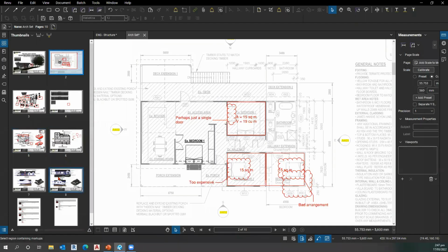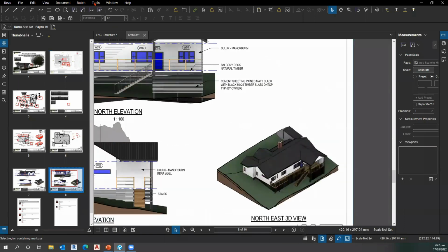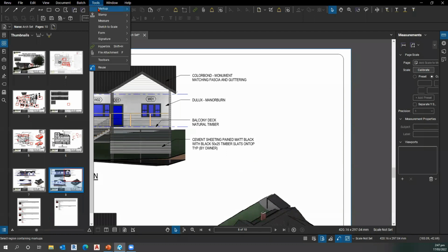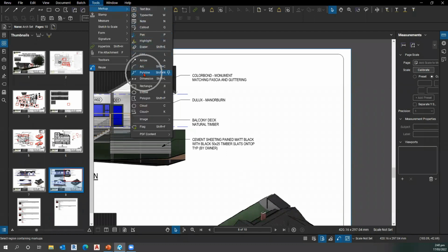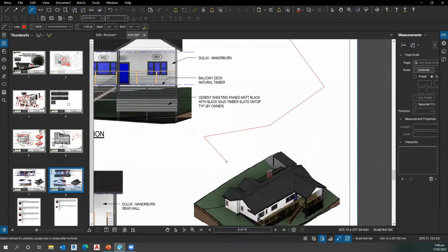Yes, this is super, super cool. All right, watch this. If I go over to my tools and I go Markup, a good example is something like Polyline. I see this a lot when people are trying to create custom markups or trying to go through more troublesome areas. So when you're in drawing mode, obviously, you click, let's say I'm drawing here, click, click, click. And then let's say I click over here and I say, oh, I've made a mistake. I've drawn this line wrong.